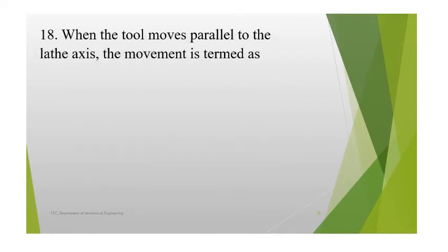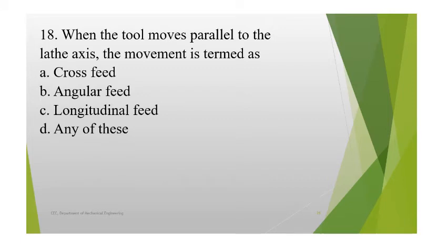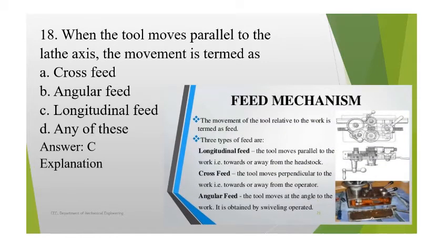The 18th question: when the tool moves parallel to the lathe axis, the movement is termed as cross feed, angular feed, longitudinal feed, or any of these. The right answer is C, longitudinal. Once the tool movement takes place parallel to the axis of the workpiece, longitudinally, it is called a turning operation. You can see this figure to understand clearly.